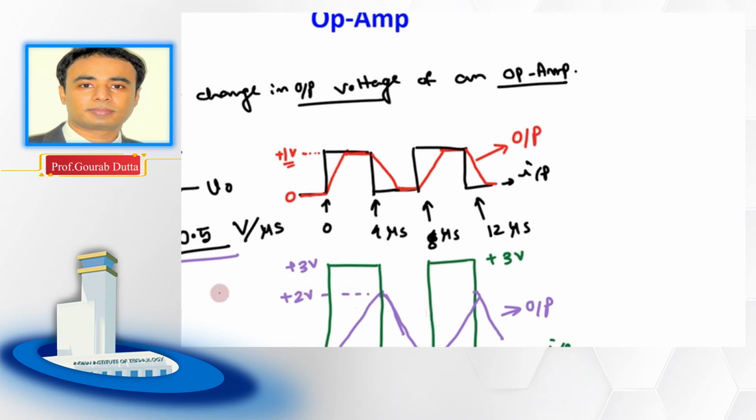So that way, two things are important. What is the input, right? The input amplitude of this input, that is definitely important. The other thing that we have seen, the input signal frequency, right? In the next case, we will also see, other than these two, the gain of this amplifier is also important, because we are considering now the buffer or the voltage follower, so the gain is 1, so that part is not coming, right?